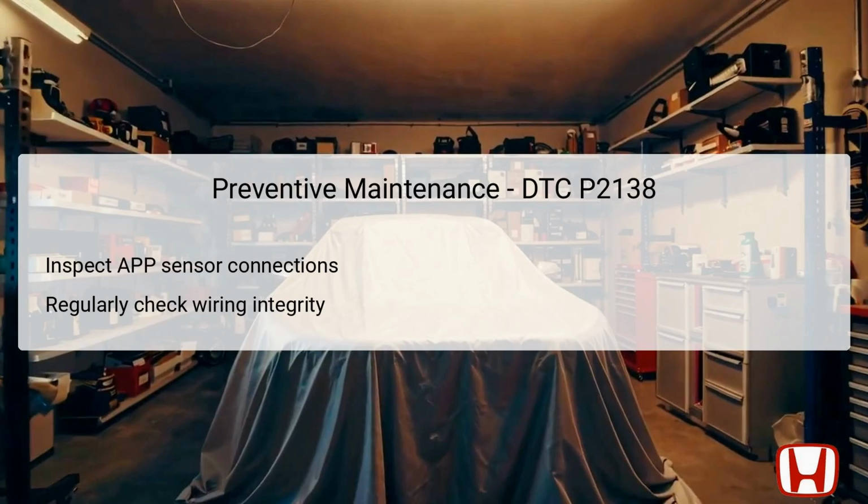To prevent the reoccurrence of DTC P2138 and ensure the longevity of the APP sensor system, consider implementing regular preventive maintenance. Start by routinely inspecting the connections associated with the APP sensors and ensuring they are clean, free from corrosion, and securely fastened.